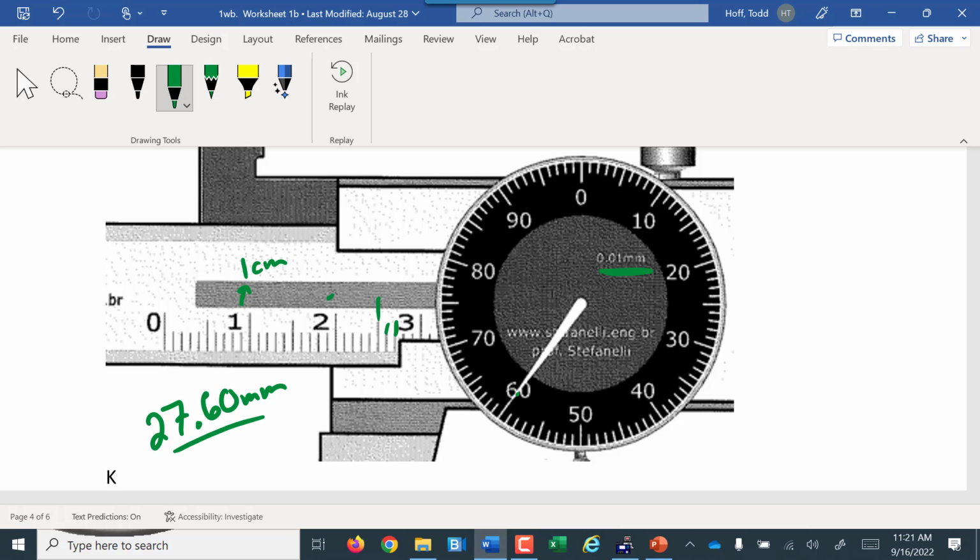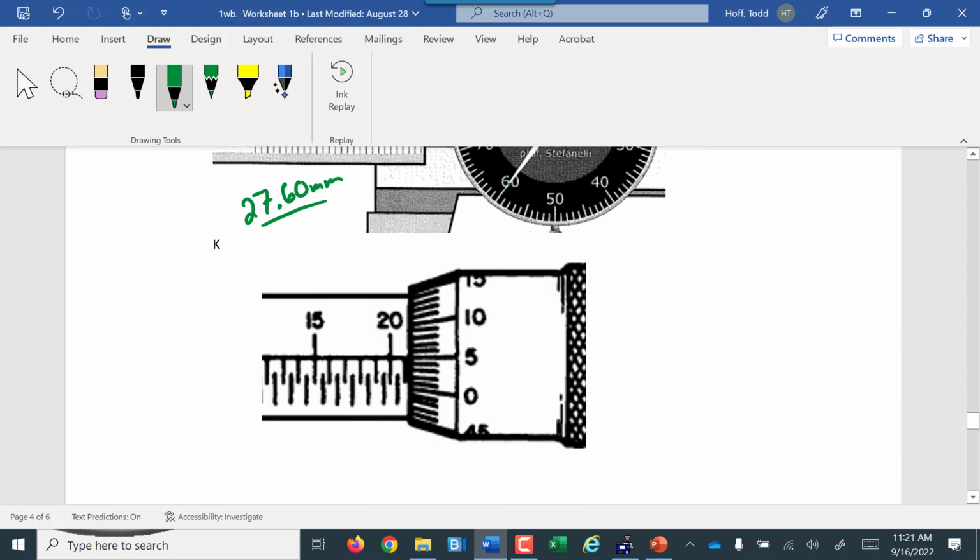The tough part about calipers and micrometers when you go from metric to standard is the decimal points in a different spot. So remembering where your decimal point goes. Like here, this is a metric or a millimeter micrometer because it's labeled in 5s here, and also it goes up to 50 before it wraps back to 0. So this is 20. This would be 20.5, 20.1. Do we know whether we've passed that line or we're just about to it?